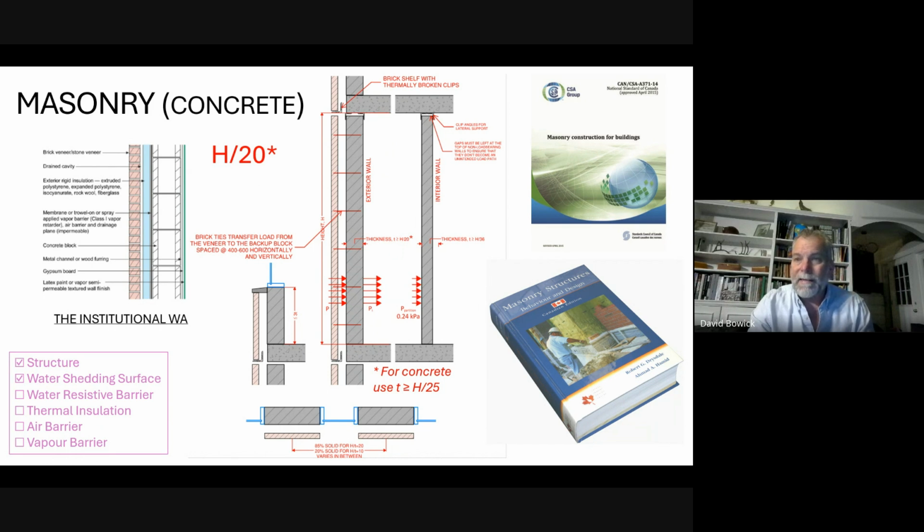And that's really what it takes to select your backup block. You can do an engineered analysis like everything else. You can do more detailed calculations. You can get slightly, generally less conservative results. But this H/20 has lasted for a long time.